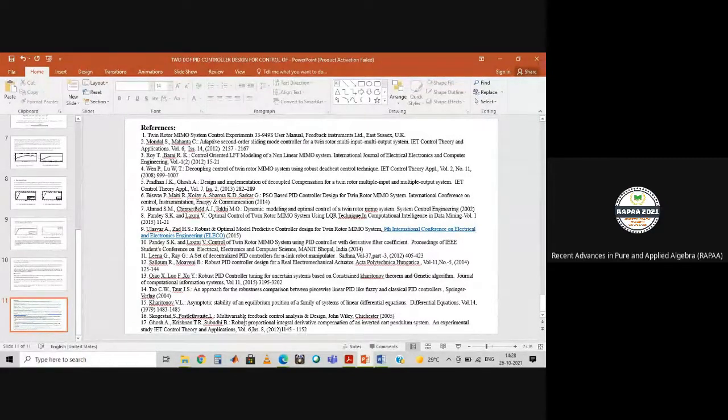Because differentiation is involved here, it may cause some noise in the data. Is that so? Sir, yes, it may occur. Sometimes I have also worked in this direction, that we can use the derivative filter coefficient in this case, and by using this derivative filter coefficient, the noise has been removed. I have also done that, and I have seen it in real time also. Okay, thank you.